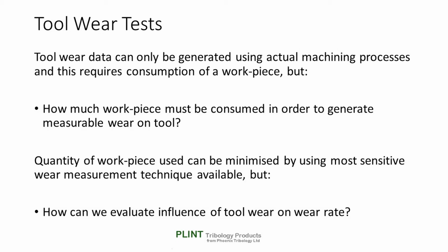Although this method allows rapid generation of wear data with an essentially new tool, it does not address the issue of tool life and its effect on tool wear rate, which will vary with tool life. As the tool wears, there will be an increase in metallic contact at the interface with a corresponding increase in contact temperature. Experiments need to be repeated after the consumption of a lot more workpiece material in order to evaluate influence of tool wear on wear rate.